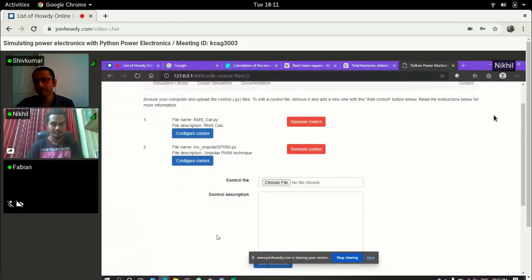Now, let's say, for example, what is your simulation time step? It is 1 microsecond, I guess. So if you're simulating at 1 microsecond, you want to capture every sample of that. You want to create a sum over half a cycle, since we know it's a symmetrical waveform. To be on the safe side, we should do it over 1 cycle, so that we have a general package that we can use anytime.